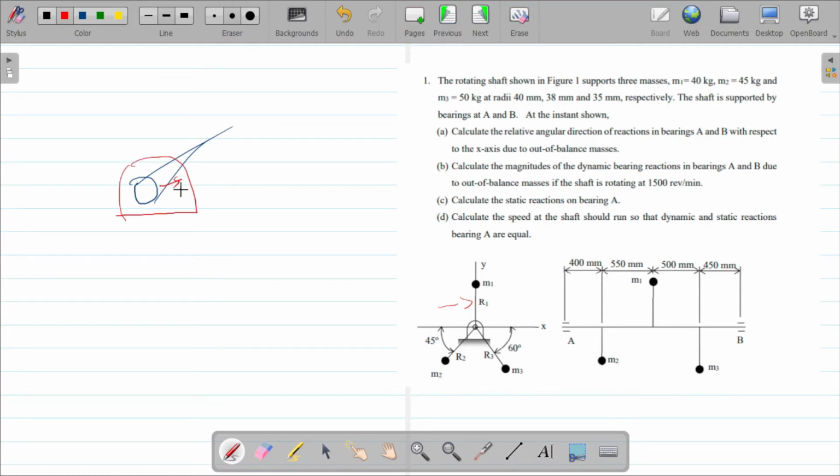The shaft will put this force on the bearing, and the bearing will put the same in the opposite direction. So what you have calculated for is the reaction on the bearing, right? So the statement wasn't too clear, but from the examples or from the notes, you can say that they are just asking us to find the reaction on the bearing. So the reaction on the bearing will just be the one we've calculated for.